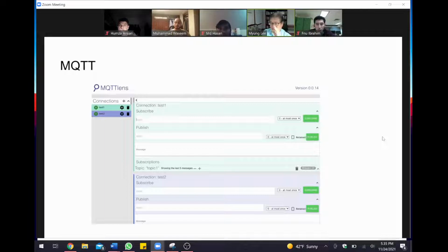That's why I was asking, because as I said, some other people are using MQTT without having a PC. The Raspberry Pi can be the server, and the mobile phone could be the client, or the other way around. I think the MQTT server will publish, and then it can connect to multiple devices. From the Raspberry Pi it will be the MQTT server sitting there, and the client is a mobile device, and maybe other sensors. So that's how you do it.